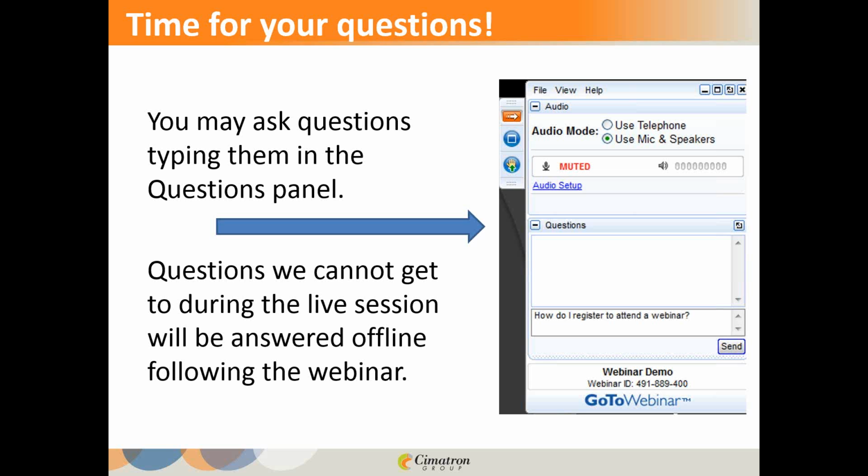Well, in that case, it'll show you what's going to happen, and you can take this information back to the customer and say, look, we know with our experience and what we're seeing, you can't form the part the way you've got it designed. You have to allow some considerations in these key areas, such as the radiuses. It is what it is at that point. The material is going to act like the material. So you can make adjustments to the gauge thickness, the material type, all that, but that's the kind of thing you have to go back to your customer on to get his approval anyway.